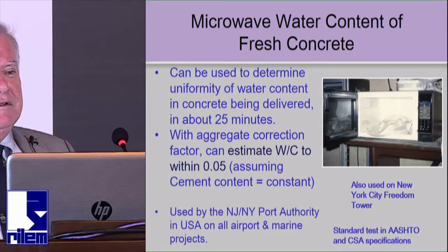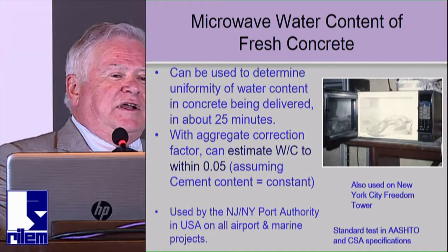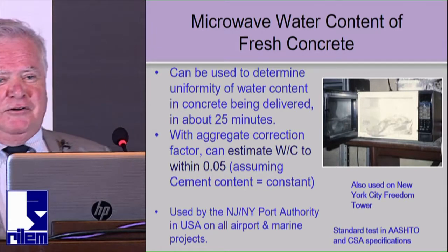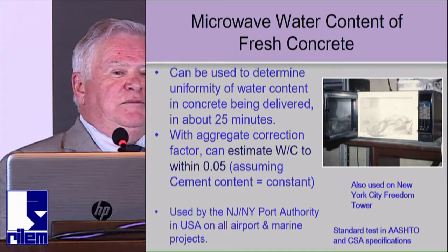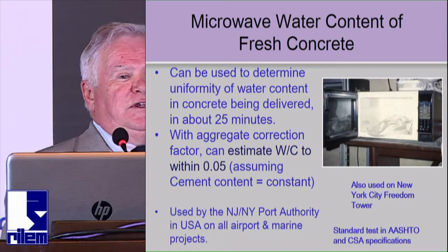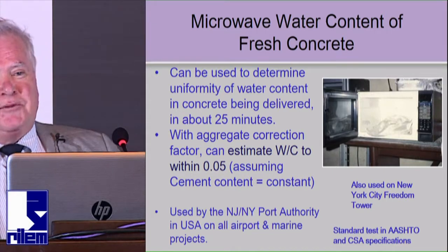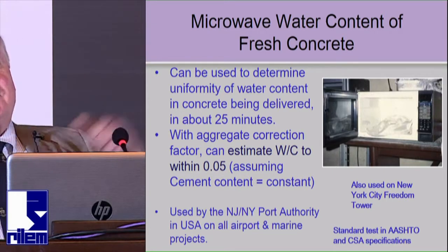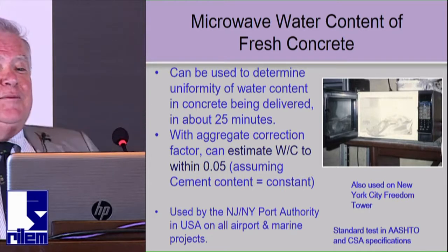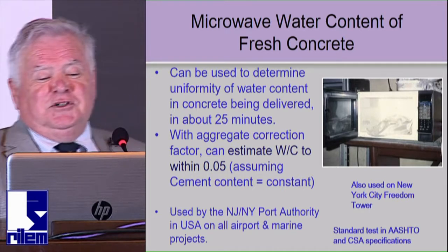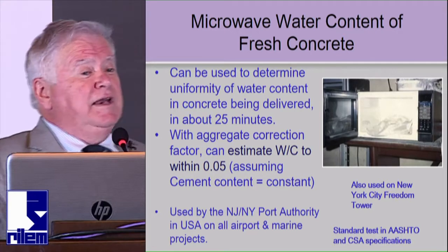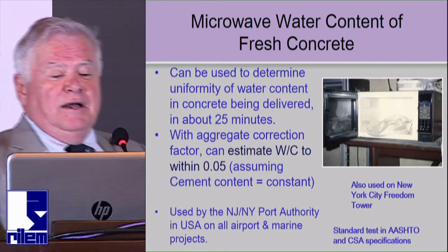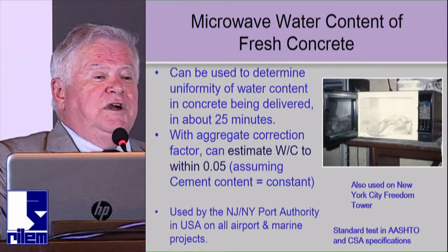It's not perfect, but in about 20 minutes you can determine the water content of the concrete, because the biggest variable in delivered concrete is the water content, because there's water in the drum of the concrete before it gets filled with concrete. After they put the prescribed amount of water in the concrete, the truck driver washes down the chute quite a bit, depending on how he feels and how much time he wants to spend, and extra water gets added. And of course, on site, other water can be added, but at least when the concrete's delivered, you want to know if the water content exceeds the specified water content,